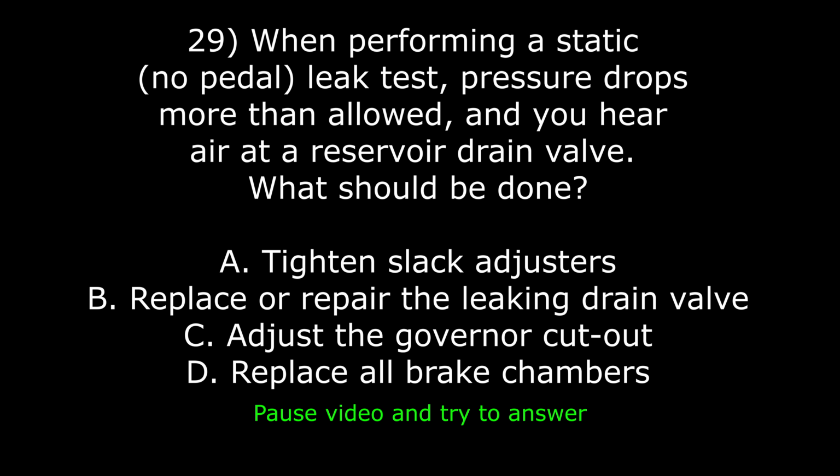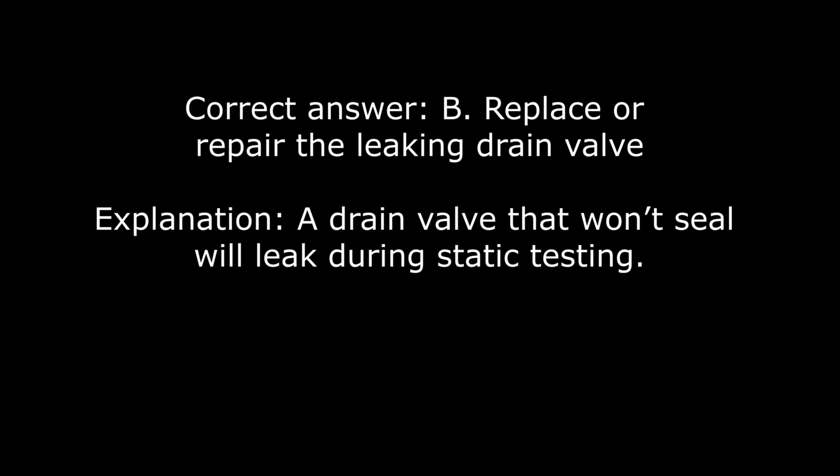29. When performing a static, no pedal leak test, pressure drops more than allowed and you hear air at a reservoir drain valve. What should be done? A. Tighten slack adjusters. B. Replace or repair the leaking drain valve. C. Adjust the governor cutout. D. Replace all brake chambers. Correct answer? B. Replace or repair the leaking drain valve. Explanation: a drain valve that won't seal will leak during static testing.